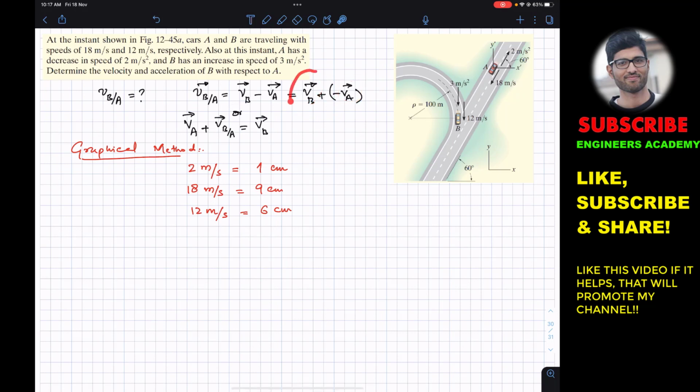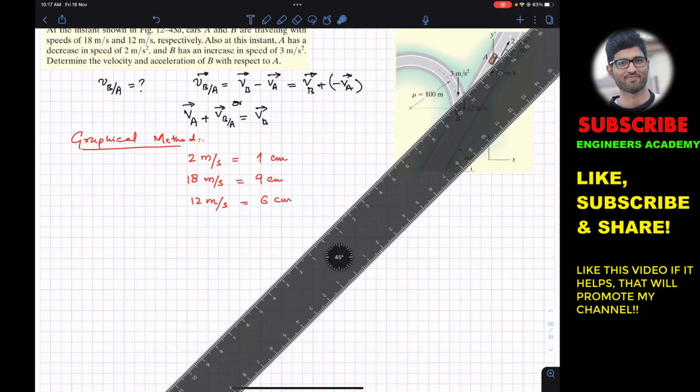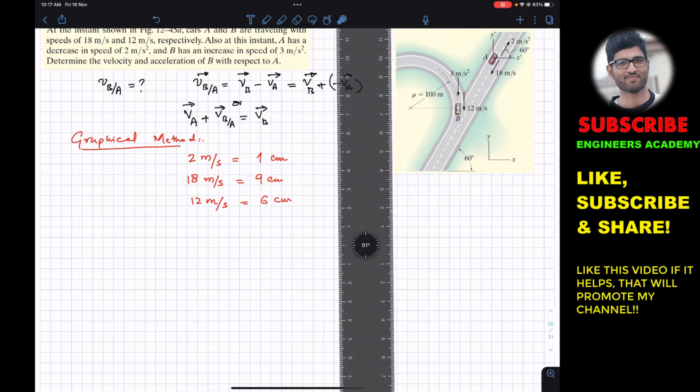So we have to draw V_B. V_B is in the downward direction. It has a magnitude of 12 meters per second, but according to our scale, 12 meters per second is 6 centimeters. So we have to draw a 6 centimeter line in the vertical direction. So now let's draw that 6 centimeter line.